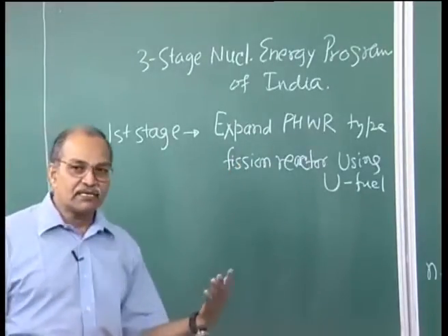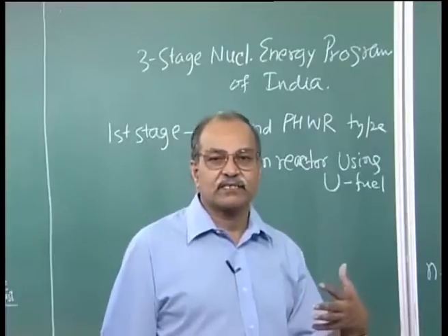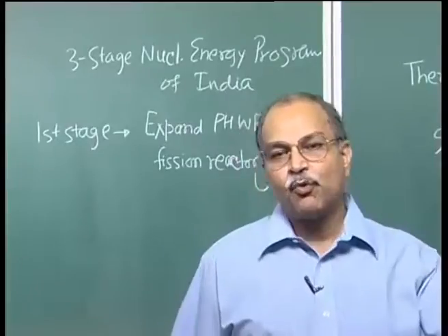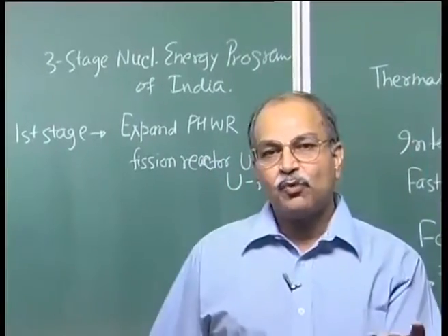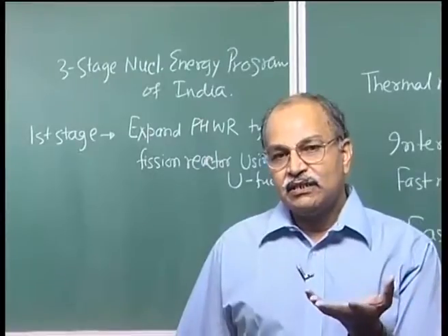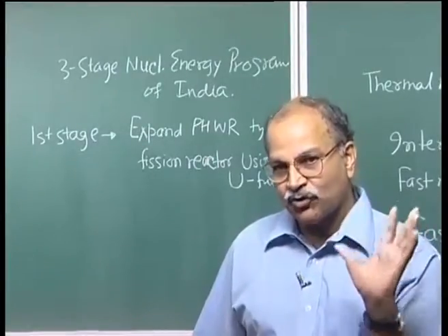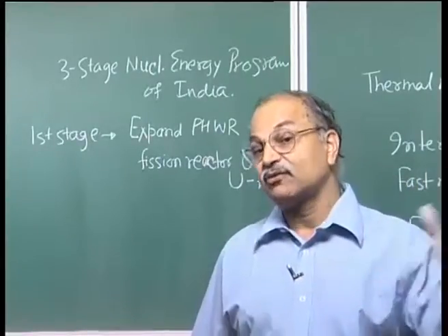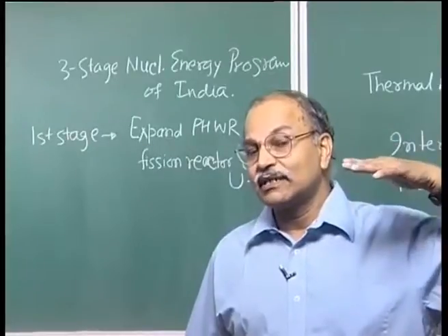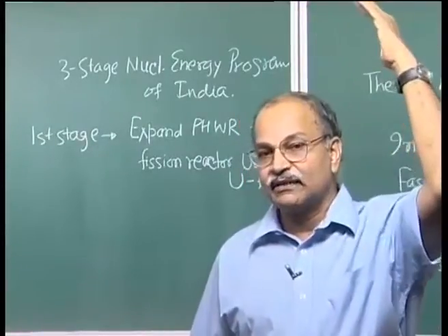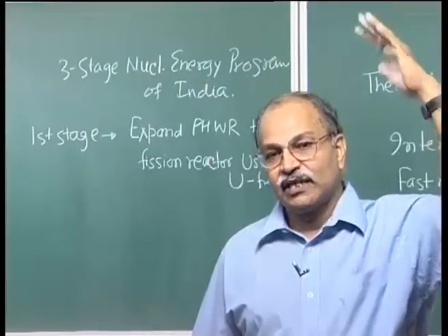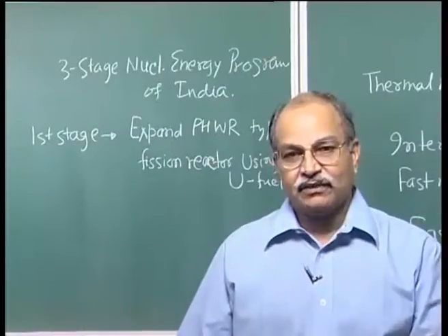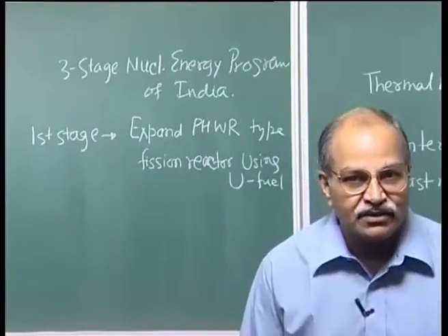Presently 20 such reactors are in use, 16 use heavy water, then 2 boiling water reactors. Boiling water reactors means the coolant and moderator, that water, boils in the core itself. The pressure is not that high, so it boils in that core itself, and the steam is taken from there to the turbine. So, that is the boiling water reactor, 2 of them. So, expand this; expand means build more reactors.